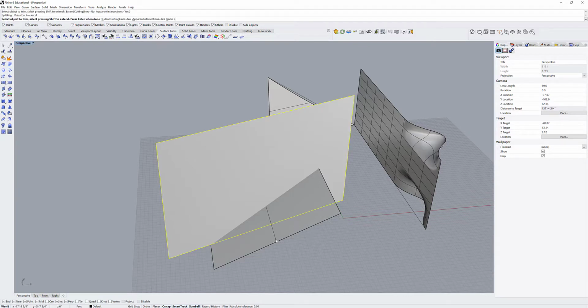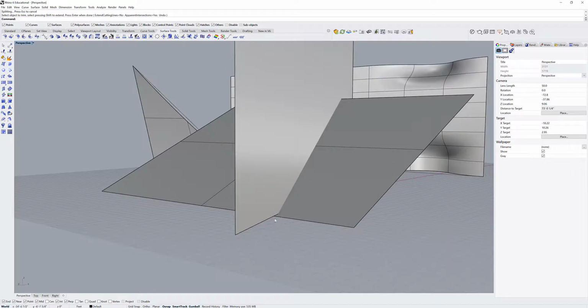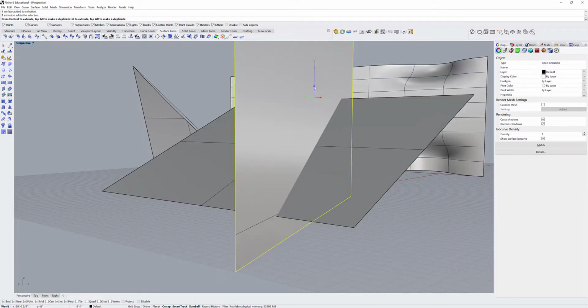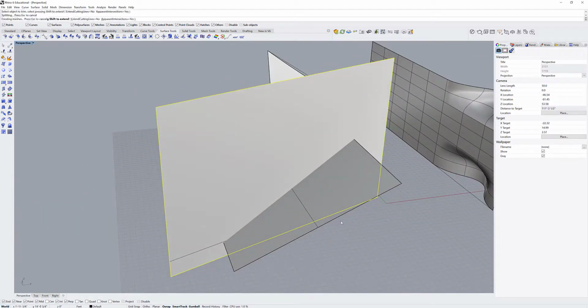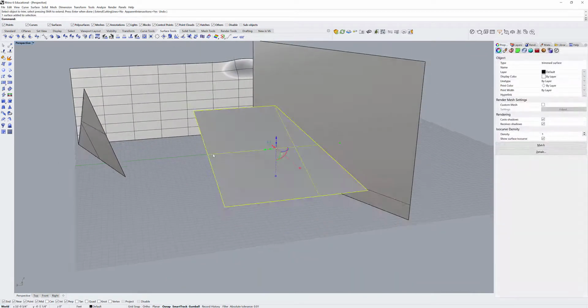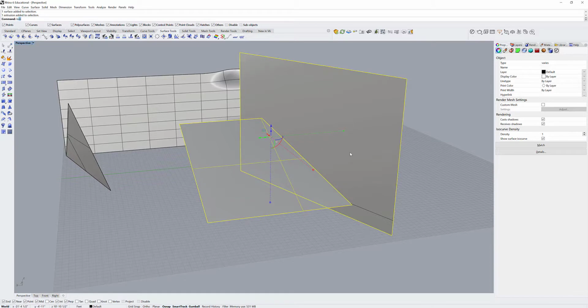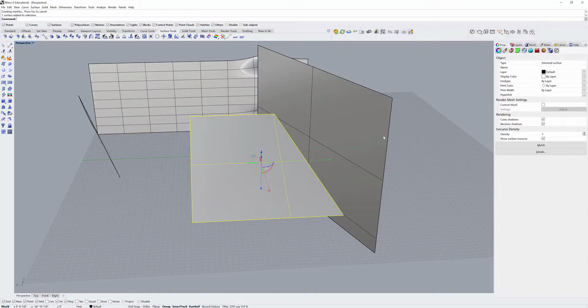I want it to be that. And it doesn't fully overlap, so let's move this up, or you can move the cutting object down and run trim again. And I want to select this object and trim out that. And now I have a clean surface. If I try to join these, it's going to tell me that it's unable to join because they don't meet at their corners.